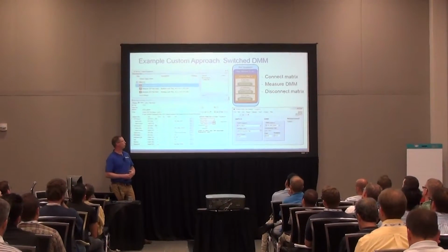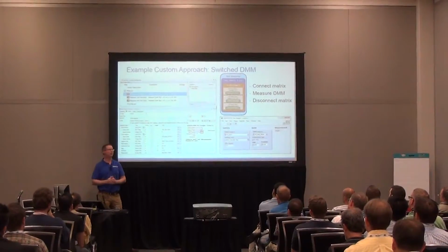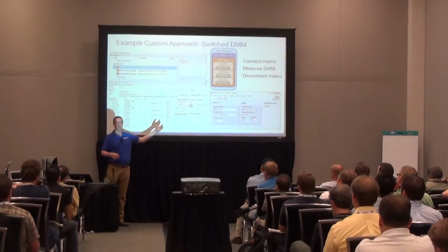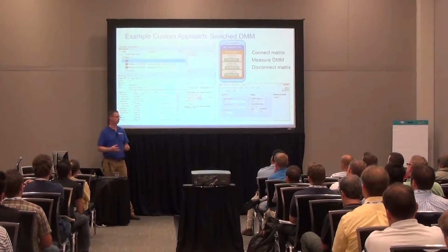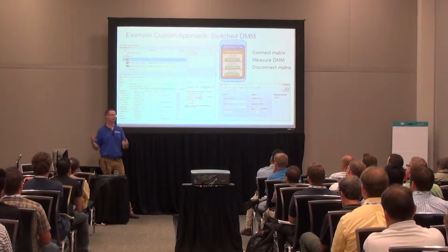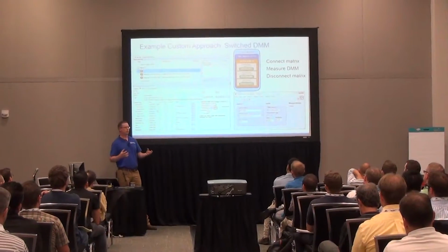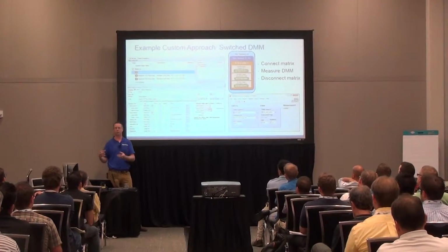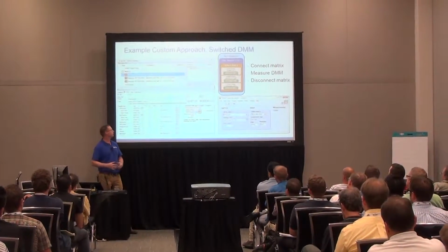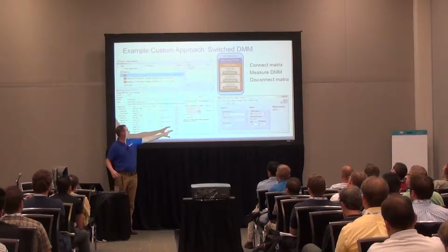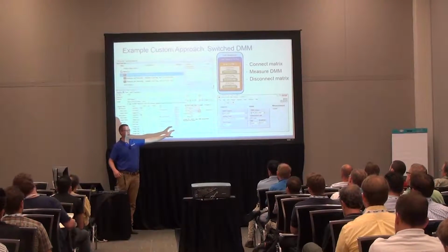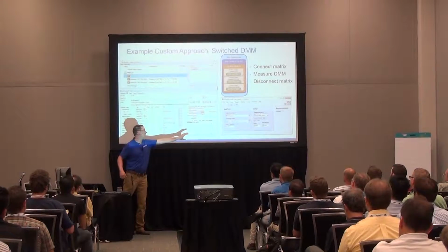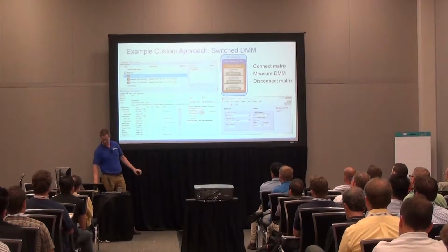So what happens if it turns out that your 2527 MUX isn't good enough and you need to put in a 2530B matrix? You need something that has more capabilities. Well, a MUX defines a single channel, and a matrix defines a series of rows and columns that need to be connected. So now, every single call to this function requires you to update this VI, which requires you to update this prototype.